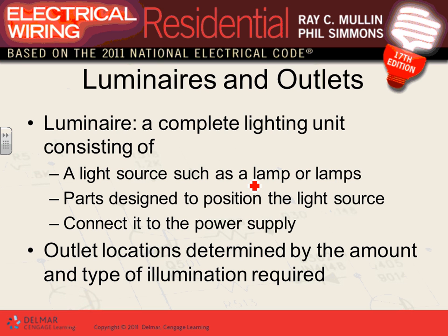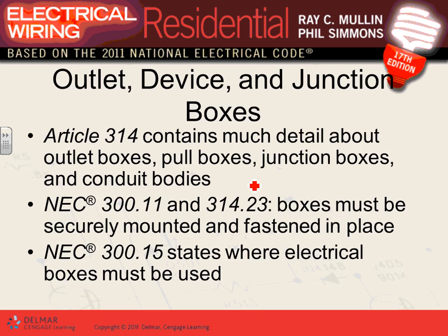In a dwelling, guys, very simple. In dwellings, every single habitable room needs one light. Where do you put that light? Right in the center of the room. Done. That's as simple as that. In a commercial building, we have software that helps us to do so.